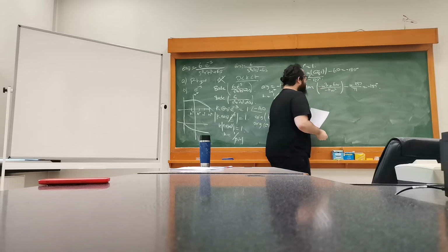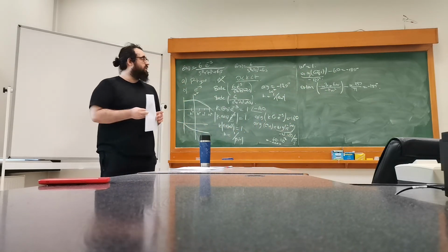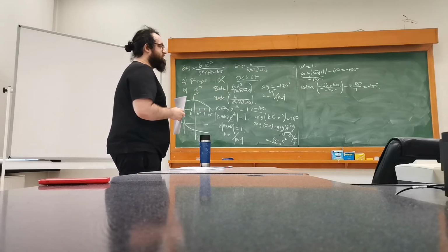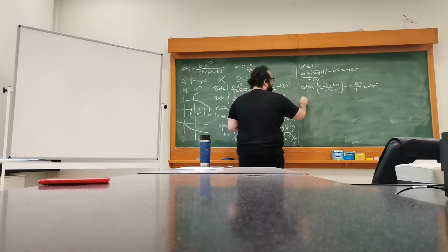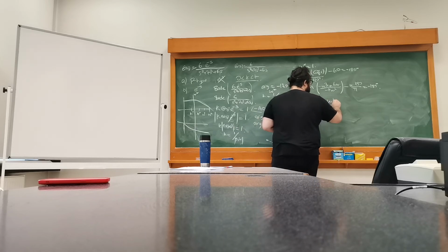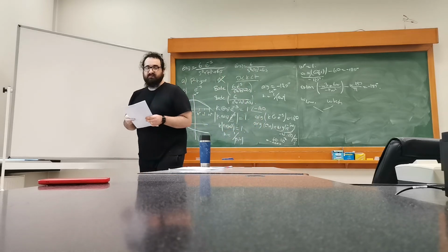So this is maybe the exact equation, but we have a tan on the left-hand side, we are subtracting some value from it, and it should be equal to minus 180 degrees. The best we can do is just try certain omega values, a lower omega value, a higher omega value, and maybe just take the mean and try to find the point where this really happens.